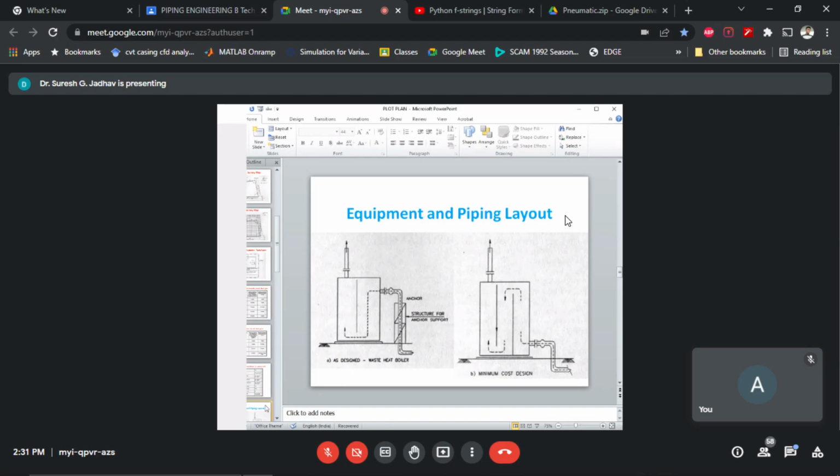The design activities took different sequences. See the sequences. The process group worked out the required parameters, did the process design of the heat exchanger and issued the process data sheet, called PDS, to the fabricated equipment group, the FEG, who did the mechanical design and issued the drawing to the piping group. The piping group located the heat exchanger and designed the inlet piping and also did the flexibility analysis of the same piping as it is subjected to high temperatures.